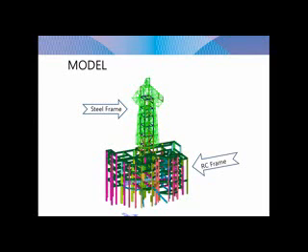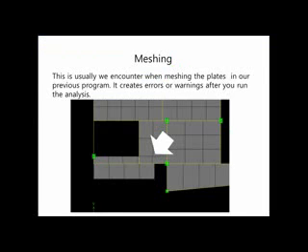Since it is irregular in shape, we just do a rectangular plate in every node, and it automatically snaps to the other nodes. We don't experience any error, especially in the node connection of plate, beam, and plate.